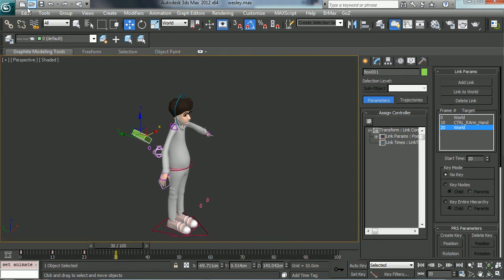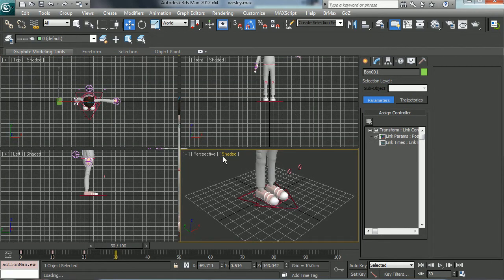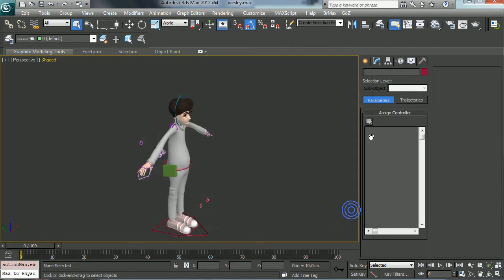Okay, so now the final one is probably the most complex, and this is using position constraints and so forth to get what we want. The time when you would want to use this is, say for example, you wanted the object to follow the hand or follow the wrist, but then you were going to position and adjust the hand as a whole relative to the object.